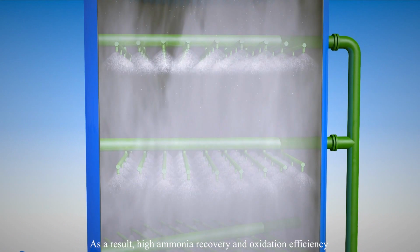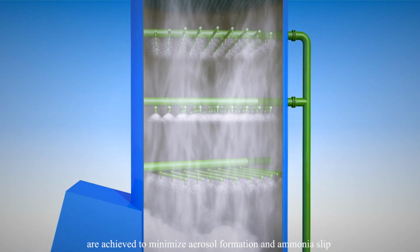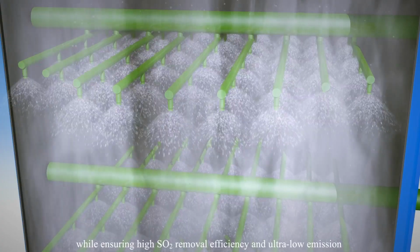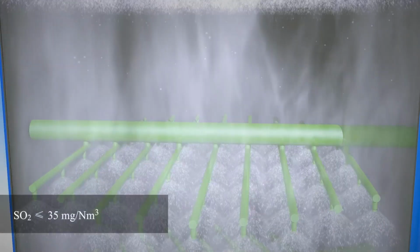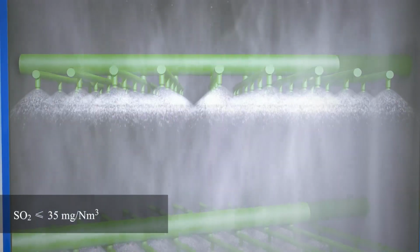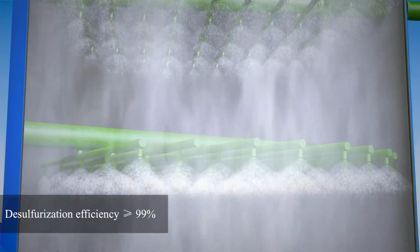As a result, high ammonia recovery and oxidation efficiency are achieved to minimize aerosol formation and ammonia slip while ensuring high sulfur dioxide removal efficiency and ultra-low emission. The guaranteed sulfur dioxide emission is lower than 35 mg per normal cubic meter, which meets the requirement of the ultra-low emission regulation, and the sulfur dioxide removal efficiency is more than 99%.